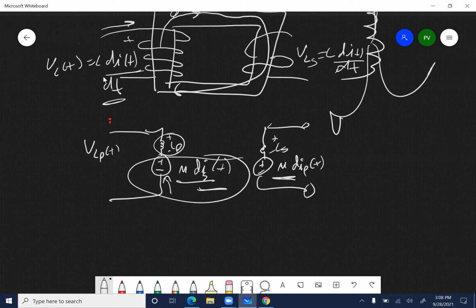Yes, sir. Does the efficiency of the transformer differ if you're trying to step down or step up the voltage? Good question. Does the efficiency of the transformer change? The efficiency of the transformer doesn't change. In an ideal transformer, there are no resistive losses. So it doesn't matter how much up or down you're going, as long as all that magnetic field stays within the core of the transformer and gets fully what they call linked, then efficiency doesn't change.